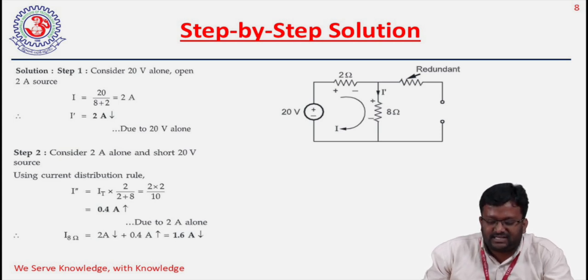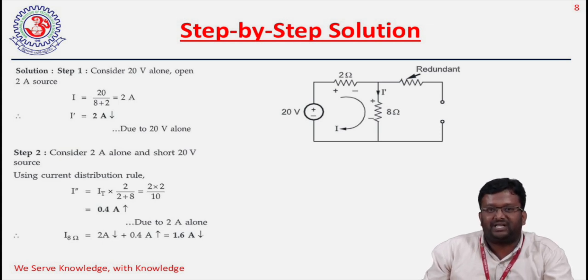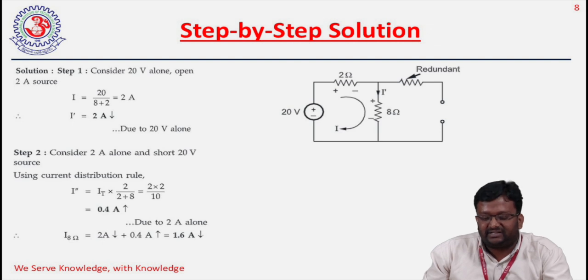When we consider the 8 ohm resistor, we need to find the impact of the current source on this 8 ohm resistor. So when we calculate the current through this 8 ohm resistor, which one is the opposite resistance? The 2 ohms is the opposite resistance, divided by the total resistance, which includes the 8 ohm resistor where we are finding the current, so 8 plus 2.